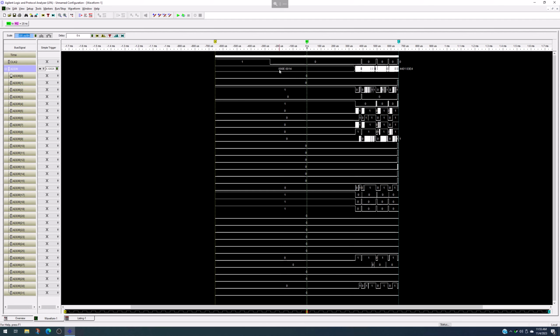But I can see that at one point it was reading out an address value of E0014. And that's good because that's a value that I know is within the program that's running. It's basically looping through, reading a piece of memory, incrementing it, writing it back out, and then repeating the loop. And part of that code is in this address in my basically ROM data, which is E0014. So the low E's is where I copy ROM into RAM. So that's a RAM address, but it's really the program that got copied from ROM that is running. But that's good. I can see that.